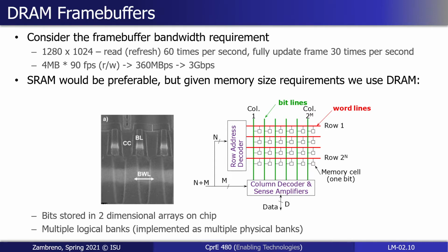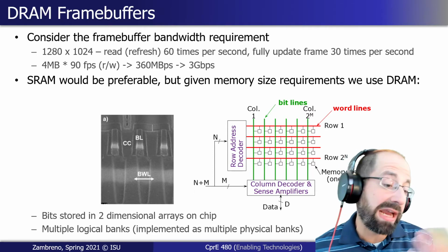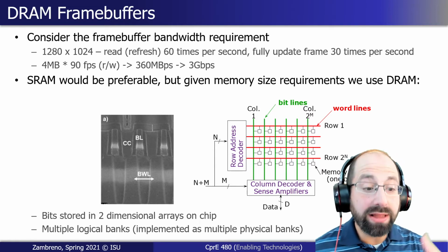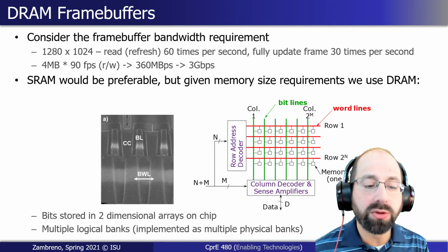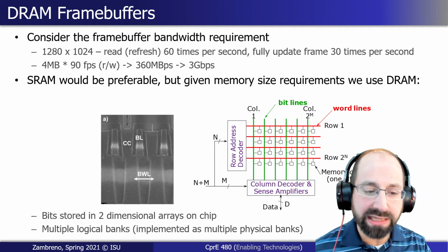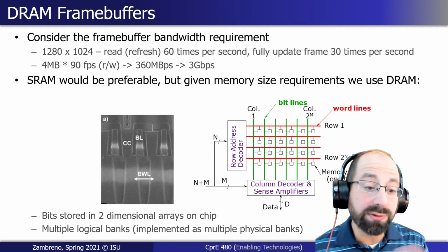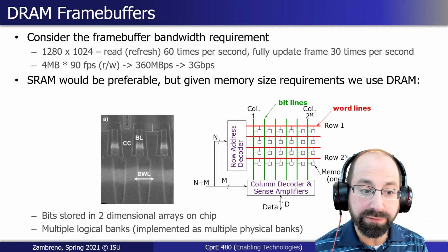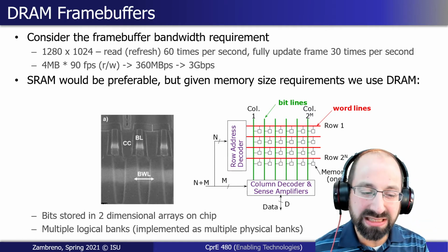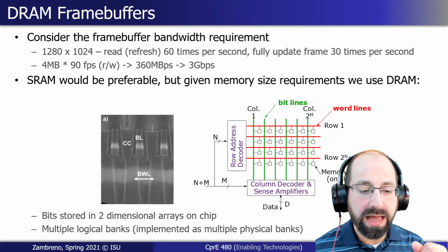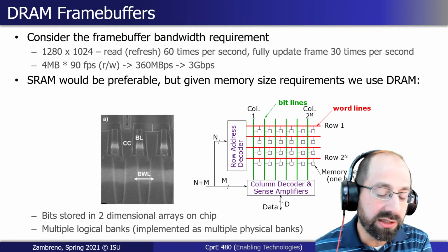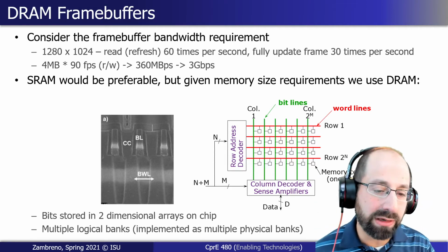There's a quick question, what is SRAM actually used for? Well, certainly for cache. So when we want a small amount of relatively high speed storage. That's the trade off we're making when we choose SRAM over DRAM. By having a relatively small amount of that really fast, not so dense memory, so it takes up a lot of space on our chip, we can maybe get some of the benefits of that high speed without having to pay the huge budget of having a gigabyte somehow of our SRAM technology.